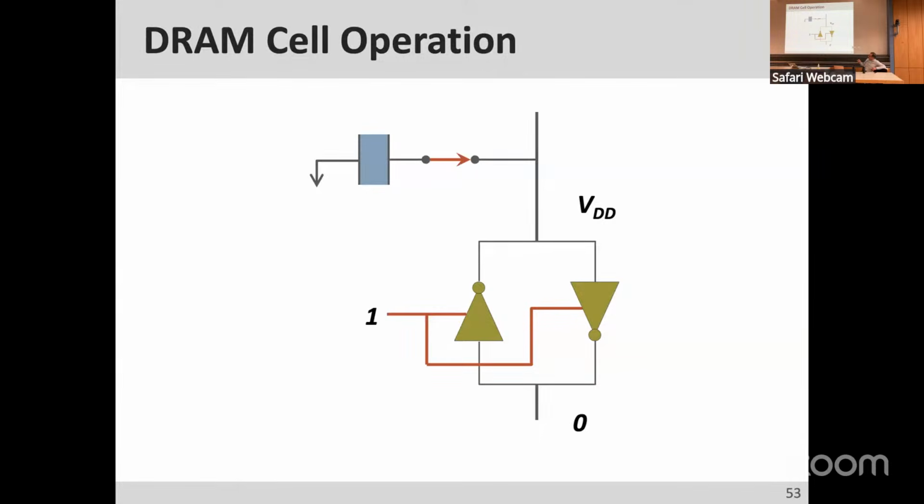And then what happens is, because the sense amplifier is very, very strong, it amplifies the voltage over here to VDD, and it keeps amplifying it. It's basically a feedback loop, as you can see. Essentially, it restores the charge of the capacitor to VDD because it's really pushing electrons back inside the capacitor over there. Make sense?